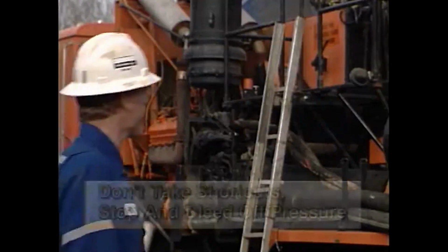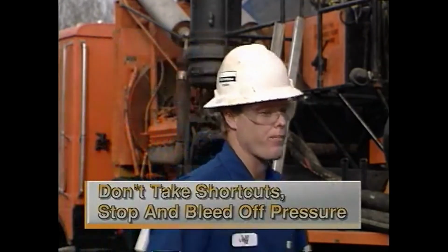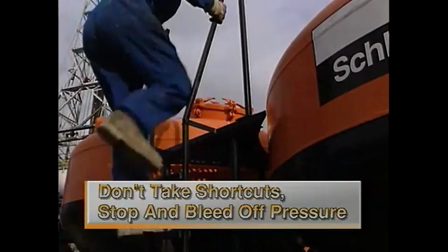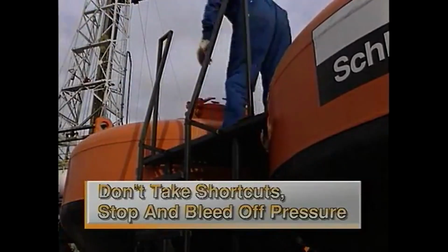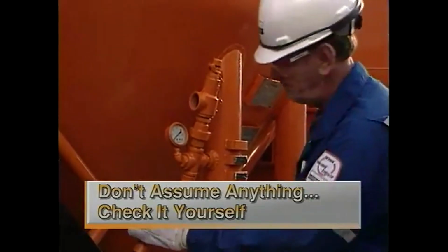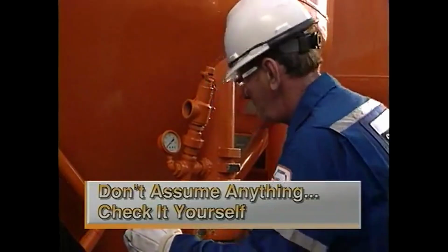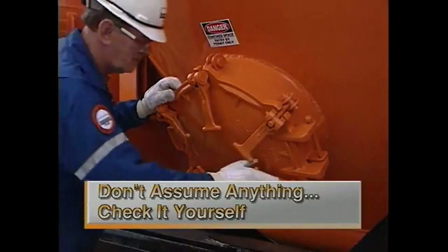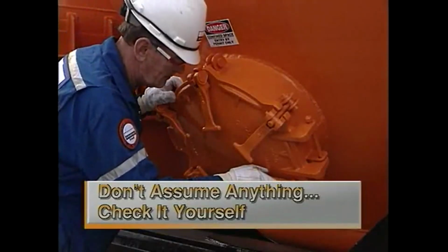So, why does someone knowingly violate the rules just given? Why does anyone expose themselves to the danger of air pressure? Well, here's what happens. Sometimes hatch covers or valves or connections start leaking under pressure. It causes problems and delays to stop an entire operation for repairs. Sometimes people assume that gauges work properly or that the pressure's already been bled from a vessel. They don't respect the pressure, and sometimes they pay dearly.